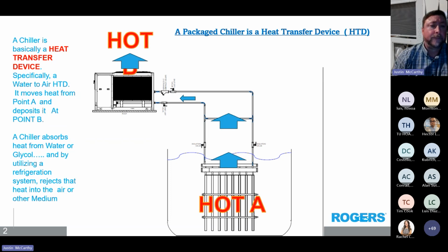In the diagram, you're seeing what's basically, it could be a tank of cutting oil, it could be a tank of hydraulic oil, or it could be an acid bath. And what we're doing there is immersion cooling. So basically, we've put a multiple plate heat exchanger into the tank, and then we're pumping cold glycol through those plates, absorbing the heat, pulling the heat from the tank, and rejecting it at the chiller.